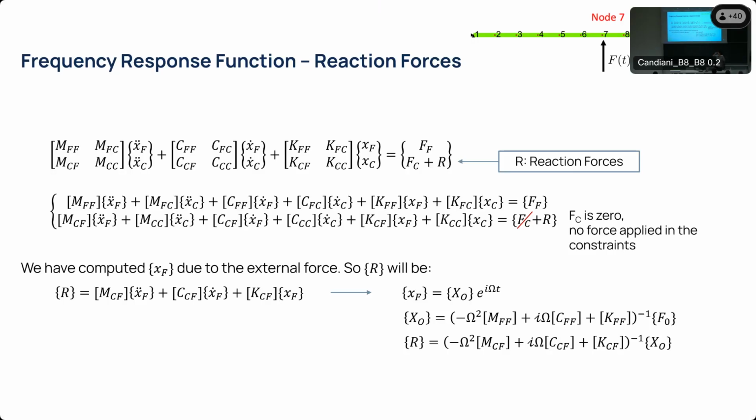Okay, last thing we have to do for what concerns frequency response function is to find what happens when we want to obtain the reaction forces of the structure. And in this case, we have to remember, we have to go back to a partitioning of our matrices to find what happened to the discarded part of the solution that we decided to completely ignore.